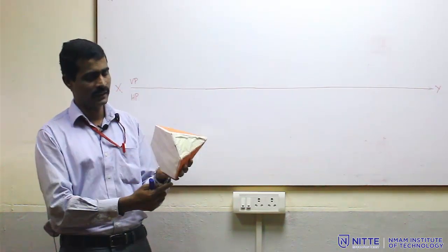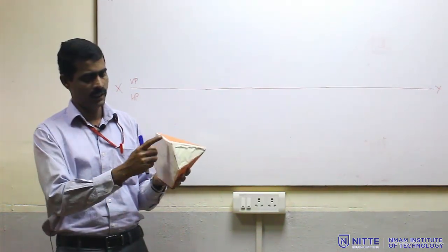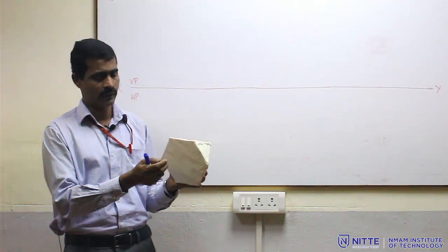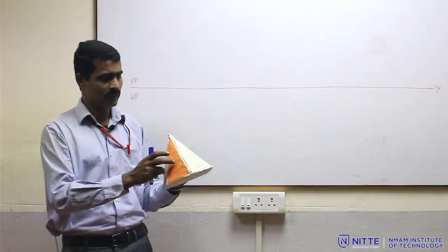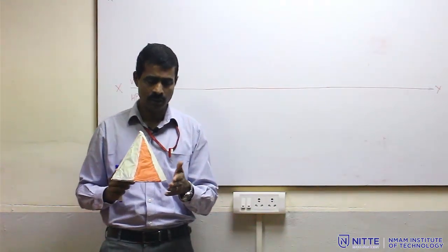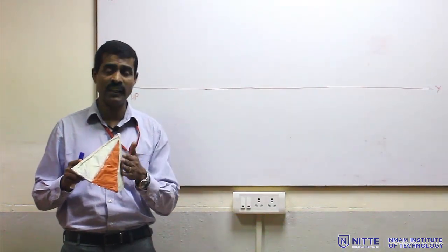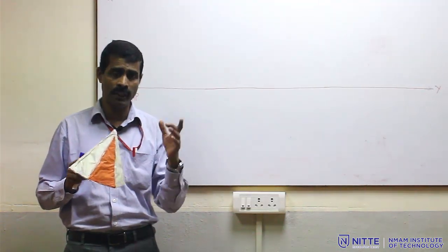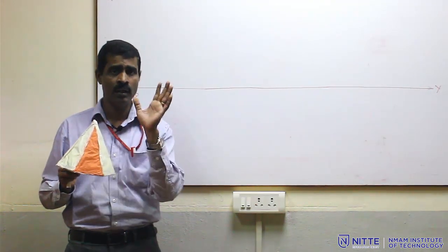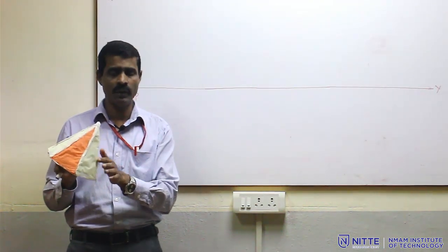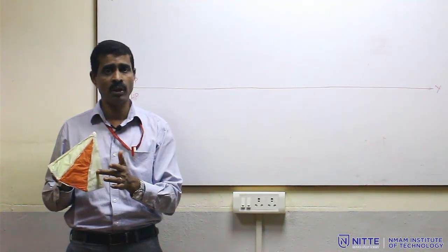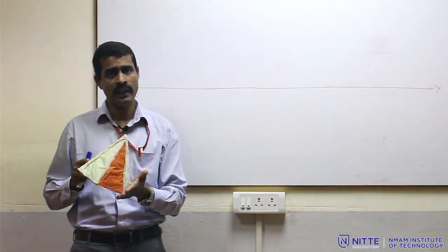Hexagonal base and 6 slant edges and an apex. So basically it will have 6 corners A, B, C, D, E, F, and O and O1, which are the endpoints of the axis, and 6 triangular faces. Now, in this particular problem, the condition given with respect to SP is the triangular face. So I told you in the beginning, when your triangular face condition is given, we have to go for the edge condition in the first top view. If the condition is given with respect to the slant edge, we have to go for the corner condition. So this is a problem on a triangular face, so we have to go for the edge condition.